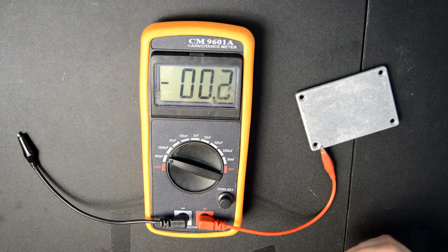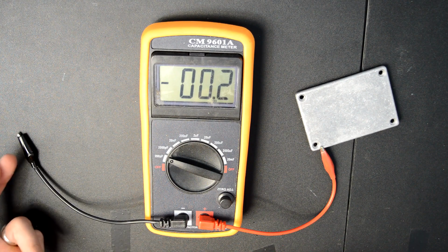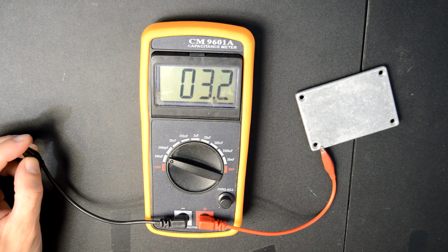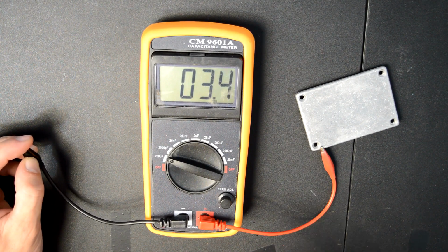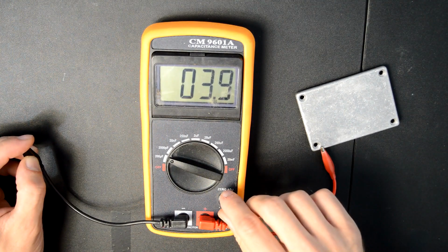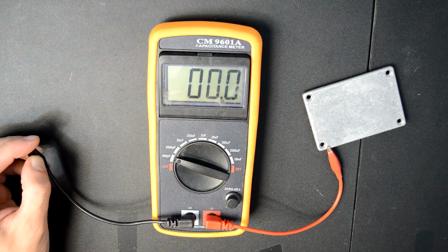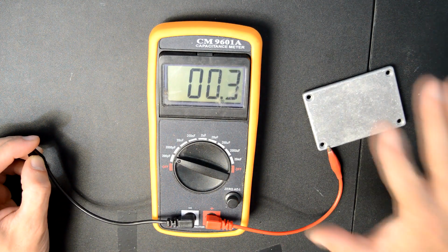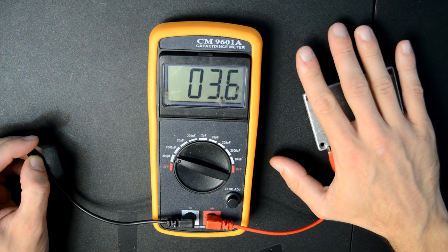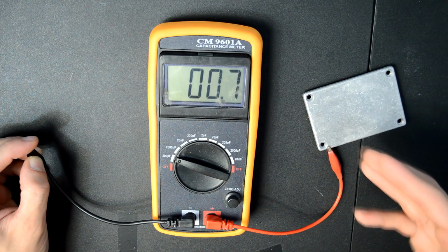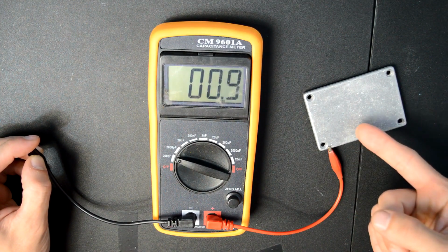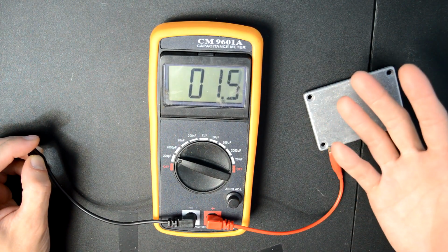Now we can make this work even better if the other terminal of the meter is grounded, so connected to me. In this case our initial capacity is already much bigger, around 3 picofarads, but that can be adjusted of course. And now if I bring my hand closer, we get a much bigger capacity being measured. Basically what's going on is that I'm building a capacitor in which one terminal is this piece of metal and the other terminal is my hand.